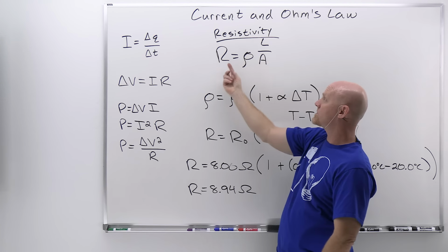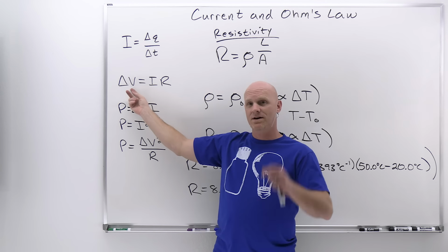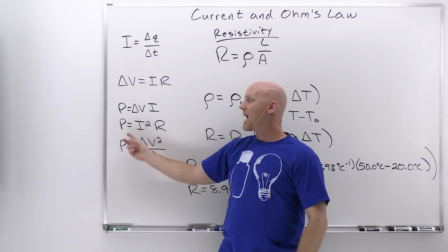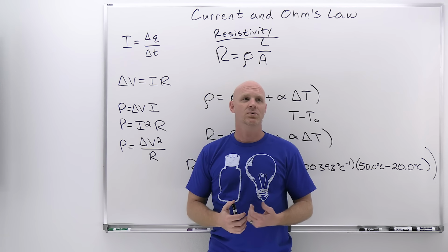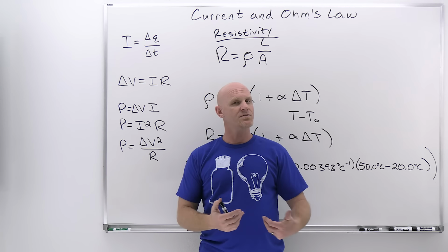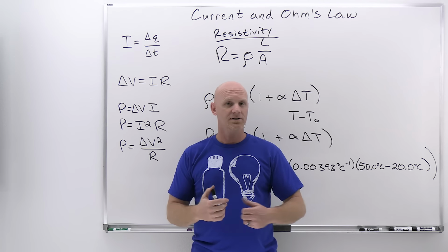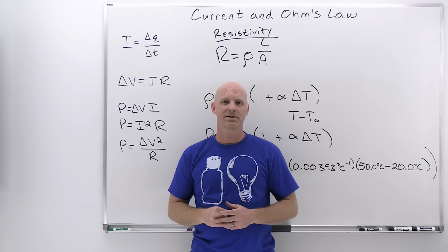And that great length corresponds to a great resistance. And that great resistance corresponds not only to a great potential drop, but a great power being dissipated across those power lines as well. And so a real increase in efficiency would be possible if we could replace all those power lines with superconducting power lines. Not presently possible, but maybe, just maybe, in the future.